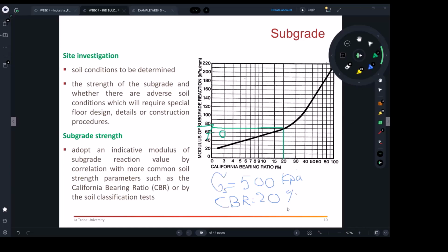Yeah, and then that is 7 millimeters, the soil, the subgrade will be settled, kind of compressed, pushed down. So let's say you have a portal frame like this, like what you are now experts in building portal frames. So let's say this column here is pushing by, I know it's a very big number, by the way, 500 kPa, but I'm just giving you an example. So that means the soil here will be settled by 7 millimeters. Then it's up to the design engineer to say if this is acceptable or not.